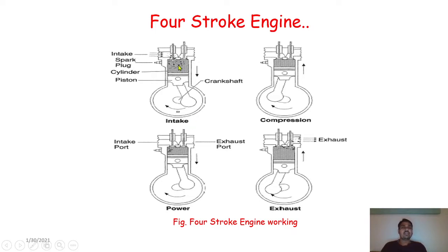Suction means what? Take the example of the process of suction: whenever the piston moves from the top portion to the bottom portion, some amount of vacuum is created inside this chamber, and because of the creation of vacuum, the air fuel mixture gets sucked inside the engine cylinder. Such a process is called the suction or intake process. Now similarly, the second process is called the compression process.